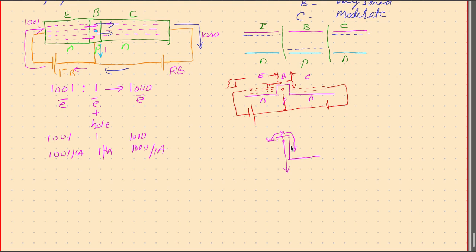And to make the fall more guaranteed, the collector valley is further deepened, and hence you can be assured that any electron which gets into the base, if it doesn't find any hole to occupy, has to fall into the collector region. Hence, to continue with the equilibrium, these electrons will be pulled out and so on.